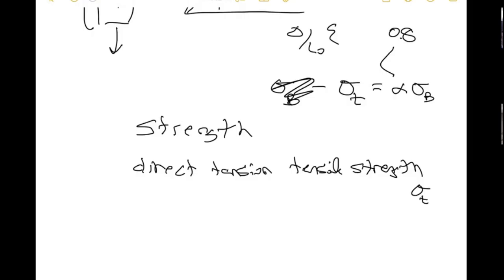And then I say to them, well, yeah, what's the tensile strength? And they say, I don't know. I say, oh my God, you don't have the tensile strength. And they're like, yeah, no, that's kind of a pain to do. We very often don't do those tests. But there's some paper where people did do that for this particular rock. And so they do have that, their UCS is 10 times bigger than their tensile strength. You're going to find that when we calibrate a bonded particle model, we will try to always start by first matching the tensile strength and then adjusting things to also match the compressive strength.